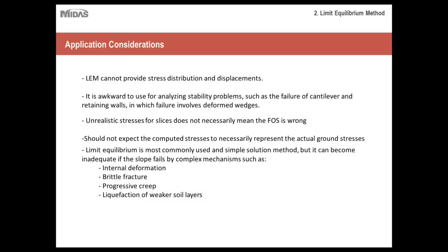But the main concept to grasp about the limit equilibrium method is that it's best suited for smaller scale, or not necessarily smaller scale, but simpler projects that don't require complex failure mechanisms to be taken into account, as well as displacements or maybe large support structures. So if you have projects that are more straightforward, that you just need a factor of safety, and it's very simple as far as the materials that are involved, then the limit equilibrium method would be your most effective choice.